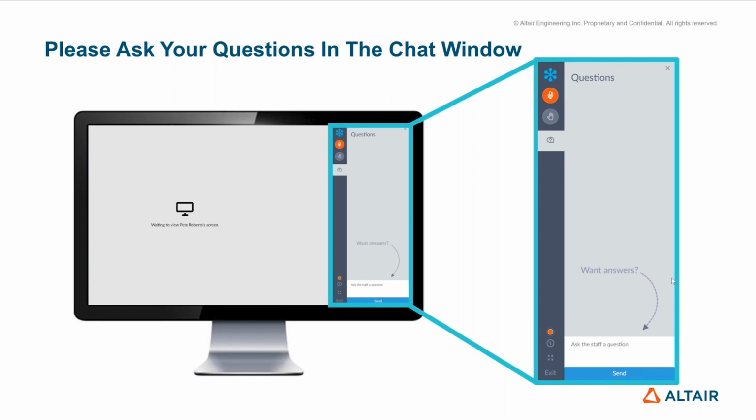Yeah, I'd add to that, Tim. I'd also talk about the hardware you're using. If you've got multiple cores, I think we have 7 cores on our processor, so we set the software to that. And you're right, it takes from 20 minutes to several hours to run a simulation. If you went through the training, you'd start with a coarse mesh, which is very fast to give you an indication, and then when you want to fine tune it, you run it with a finer mesh. Yeah, that's correct. So the number of variables: hardware, mesh size and size of parts, really.